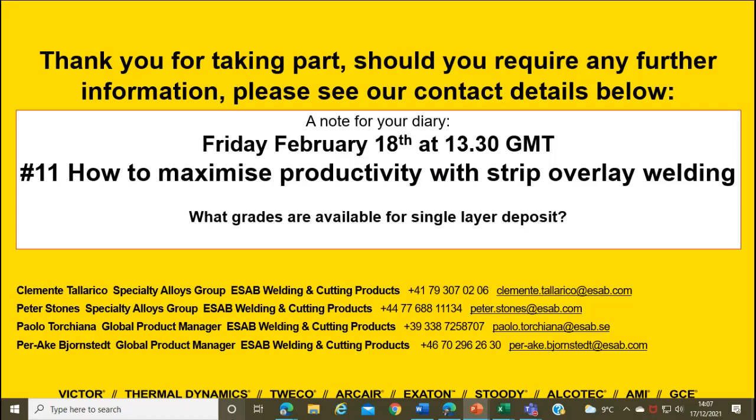Yeah. But I would also add that if we assume that the heat input is the same for subarc and electroslag, just an assumption, considering that by using electroslag fewer hours will be needed to get the job done, then at the end we will be adding less energy into the plates or into the shells. So probably the distortion should be lower with the electroslag. Yes, indeed. I agree.